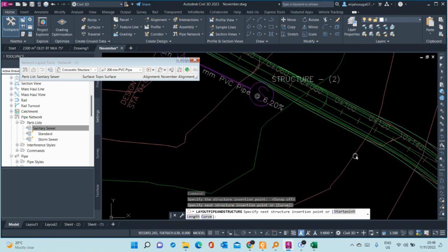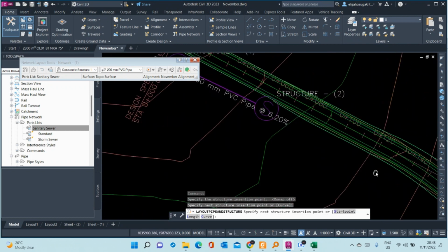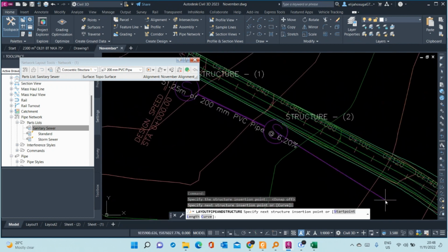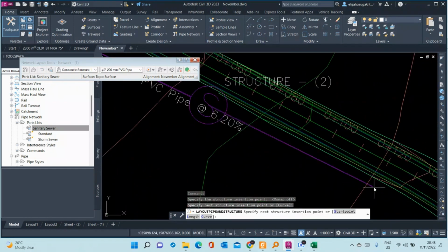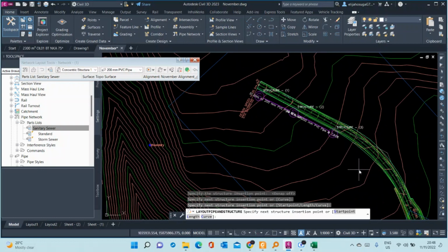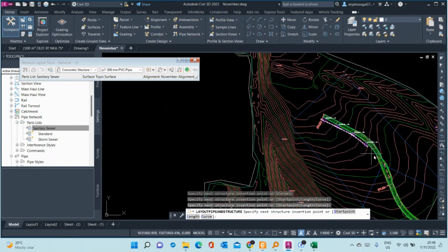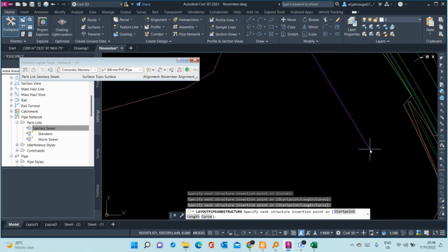There are rules that you also need to know. You should have done a length check also, for certain maximum distances for pipes between manholes. But we also know that every time you change direction, usually there's a manhole. That was taught in class.